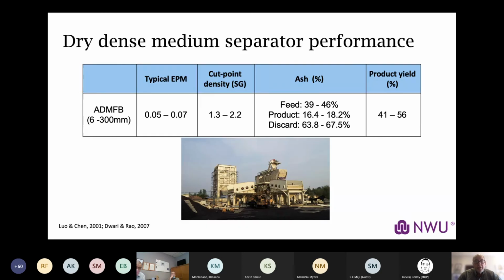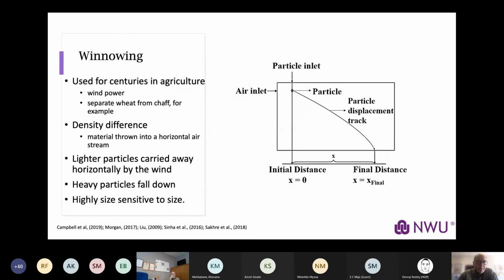And as I said just now, for some reason I heard that it had a lot to do with the moisture in the coal. You can imagine if you've got a little bit of moisture going into this bed, it's just going to choke up. You're just going to form globules. Magnetite is easily wettable, and it just forms these clots, and you've got all sorts of problems. So your moisture control into the plant is crucial, as with most dry beneficiation.